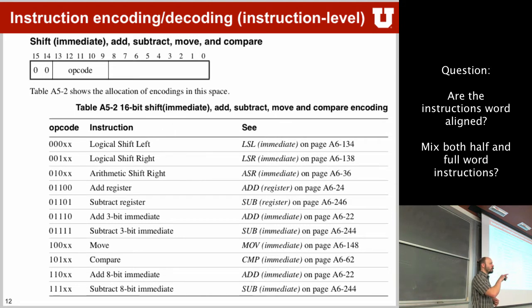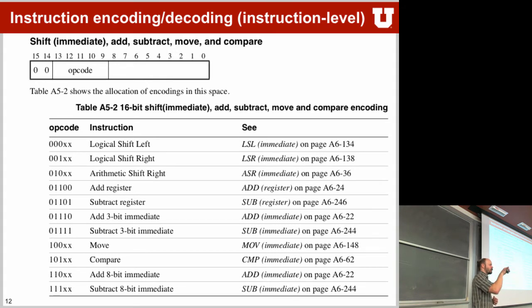Now, because of how memory access works, you always read out of memory as a full word line. So if you're smart, you will sometimes word align your code so that 32-bit instructions are actually word aligned themselves, not over the break of a half word or over the word boundary. Otherwise it will basically fetch the one word, start executing the first one, then start looking at the second one and see, oh, I have to go and fetch the other one, so first you have to do a memory fetch before you actually can start executing it.